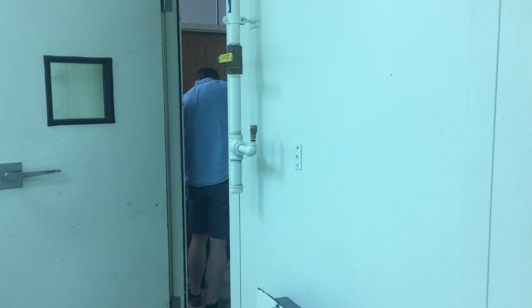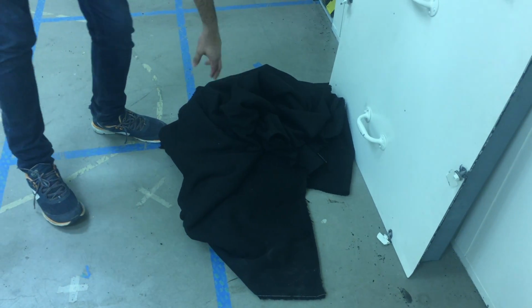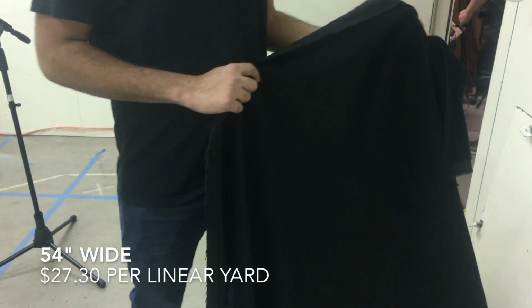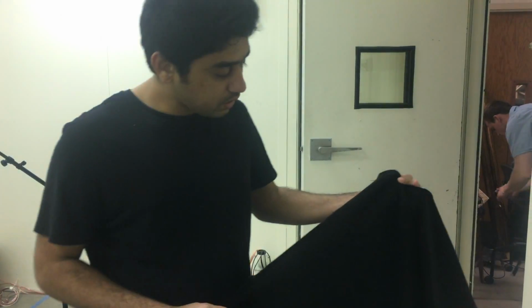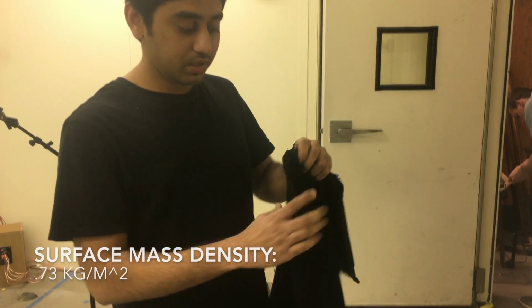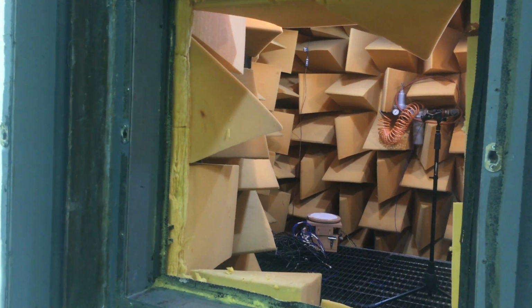Alright, we are testing insertion loss and noise reduction of the curtain material that we ordered from Rose Brand. It's a 32 ounce curtain, 100% cotton, and it's 100% nap-down model. We're going to use it with various combinations in this partition to get the insertion loss and noise reduction.